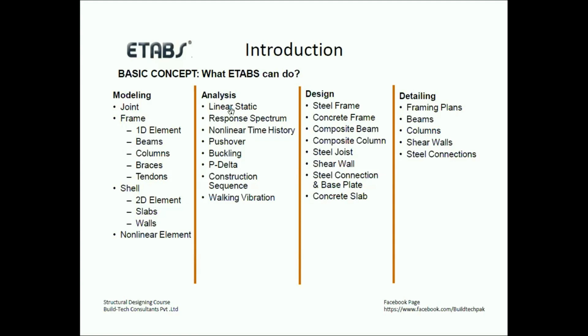In analysis, there are different seismic analyses specified by the codes, which include linear static and non-linear static, then linear dynamic and non-linear dynamic. All these different kinds of seismic analysis can be performed in ETABS. The basic one which we commonly use is the linear static procedure, which is the equivalent lateral force procedure, which is used for like 70-80% of buildings. Once you go to a higher number of stories, and there are some irregularities in the building's plan, then you need to go to some further higher seismic analysis procedure.